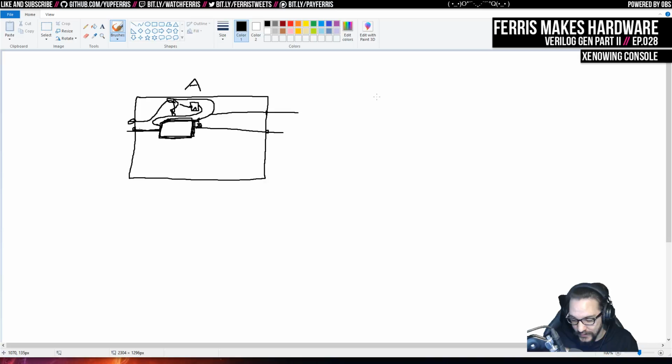I mean, the synthesis tool is going to do that anyway. But yeah, we'll see. Anyway, during that flattening pass for the simulator, it traces from the outputs, and when it sees the output of an instance, it will trace into that instance, keeping track of how it got there as well, so that it can find all the registers in there and add them to this outer part. Whereas here we actually don't want to do that.